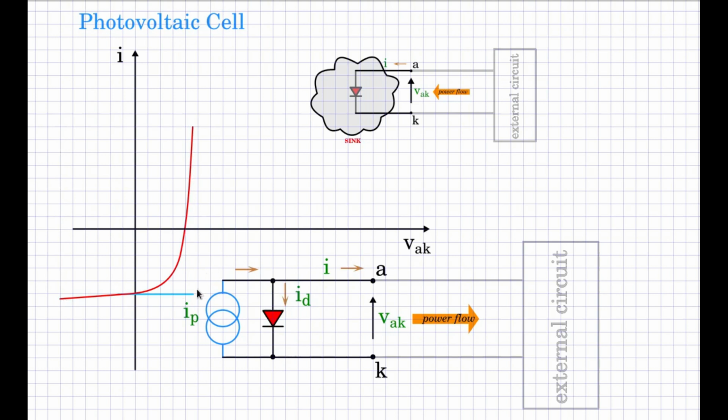Normally the photovoltaic cell is considered to be a generator, and one would like to see that it is in the first quadrant. Therefore, we now redefine the current, the voltage remaining the same. We will take the direction of the current as positive when the current goes out of the terminal as shown here, and not like what it was defined before for the case of the simple diode.